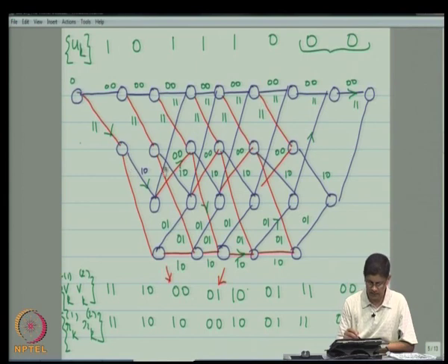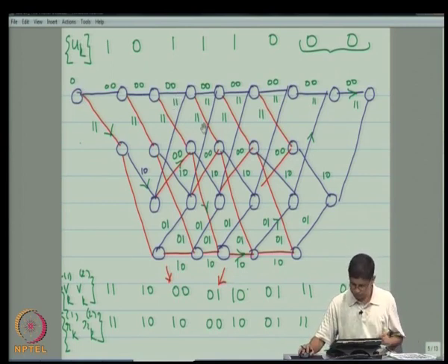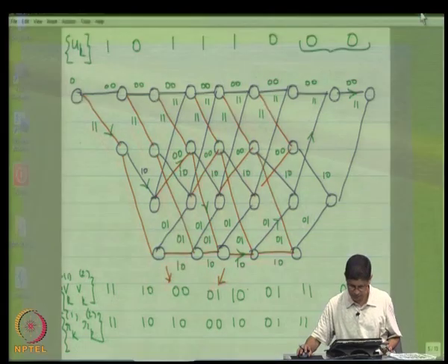The path has length 3, and the number of message symbols that are 1 is 1. So this would correspond to an L cubed I, and the corresponding output sequence has Hamming weight 2 plus 1 plus 2, which is 5. So it would correspond to an L cubed I d5 term. Okay, so that gives you some idea, I hope.